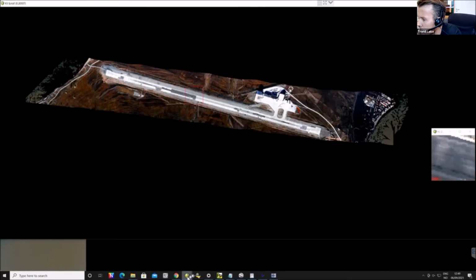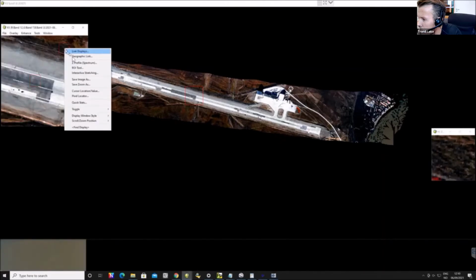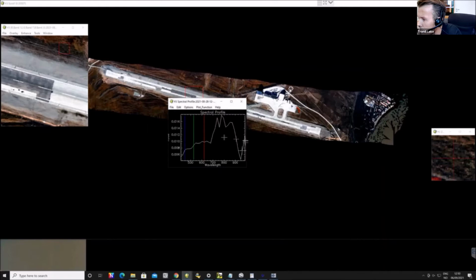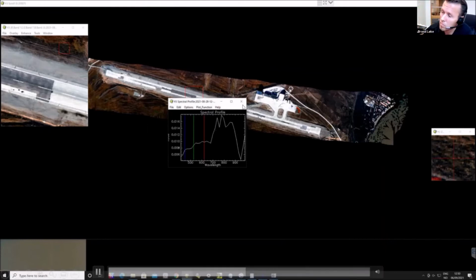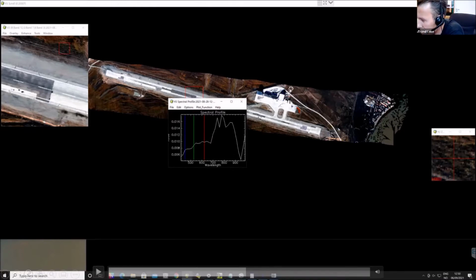Let's open the other. Yeah, you have that. Only 6 out of 30 bands now, because I've binned it 6 times, right? Okay, let's go to the Boresight. This is for the Boresight calibration, right? As I said, you don't care about the number of bands or the signal to noise ratio. So just to reduce space, I put spectral binning to 6 when I process it in Hyperspectral Rad, because then the number of bands or the file size gets smaller and the Boresight goes faster. Of course, you could also select just to rectify RGB bands here, not all 30 bands.